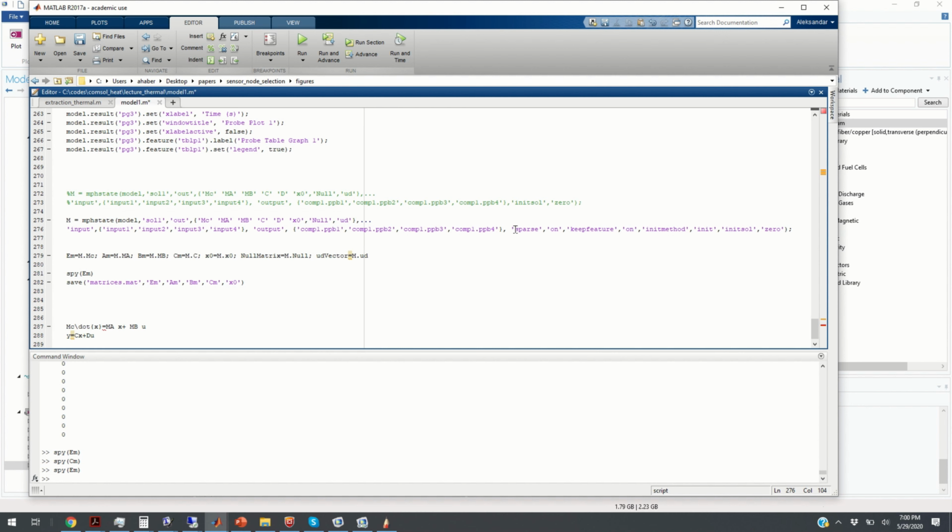Now, you need to specify here the option sparse on, since this model is large dimensional. The matrices can easily be million by million, and you cannot store this in computer memory. Even if you have a supercomputer with terabytes of RAM, it's still difficult. And here you can play with the parameters, initial solution, where you linearize, etc.